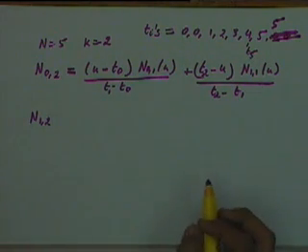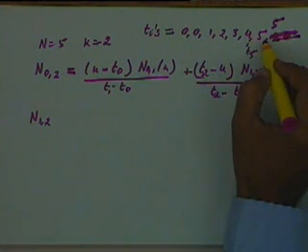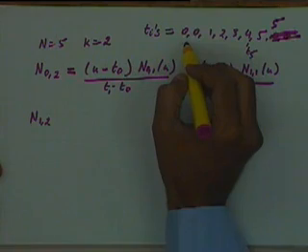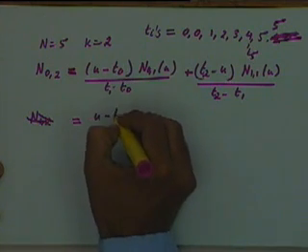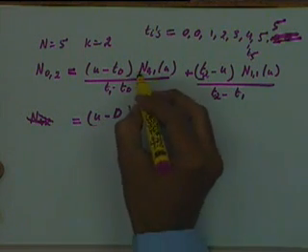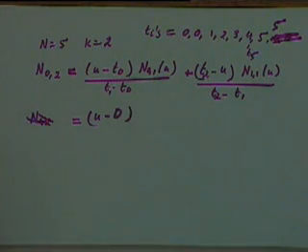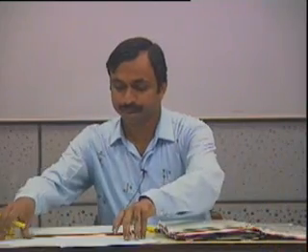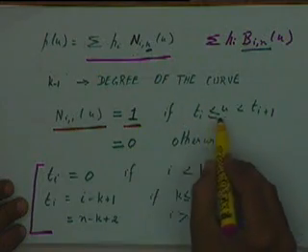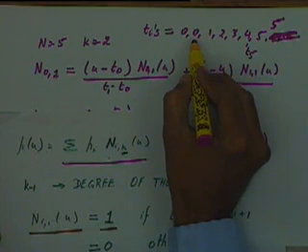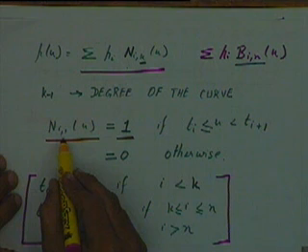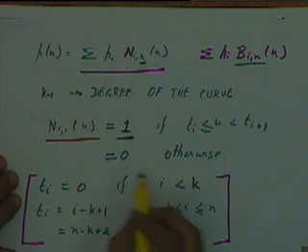So whatever be my curve that is finally defined, I have 2 knots at the starting point and 2 knots at the end point. 2 coincident knots, that is. So if I put these values over here, I will get u minus t0 is 0, so u minus 0 multiplied by n01. If we take the definition of ni1, with i equal to 0 it will be equal to 1 when u is between t0 and t1. So when it is between t0 and t1, at u equal to 0, n01 will be 0, and will be equal to 0 otherwise.